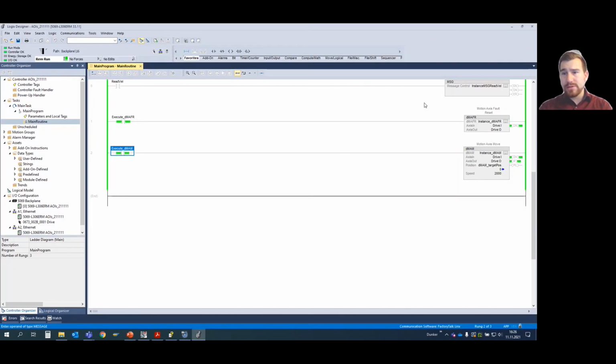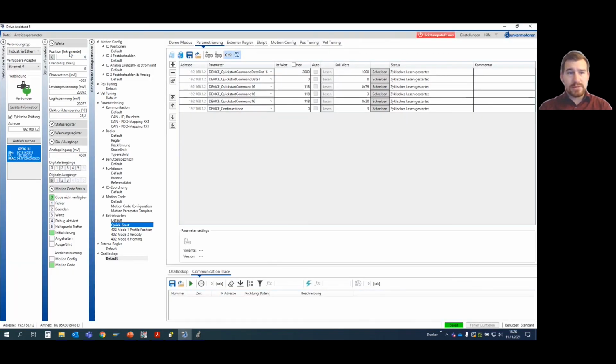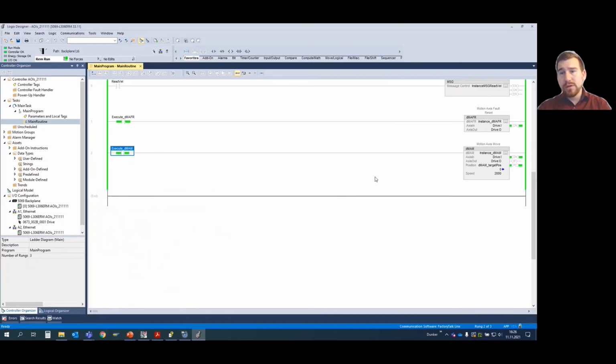I'm not sure if you can hear it. And you see here, right now, it gives back the in-process bit because the positioning is running. And when it reaches position 0, the process clear bit comes right now. This means that the position is reached. We can double check here. Yes, it's position 0 right now, and the positioning did work. So it's quite easy with these AOIs to control our motor. And yeah, I think that's it.